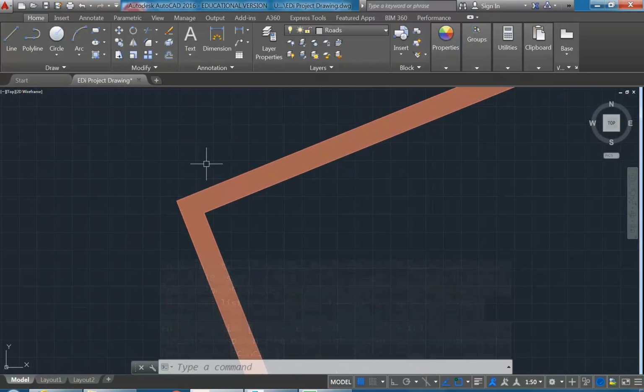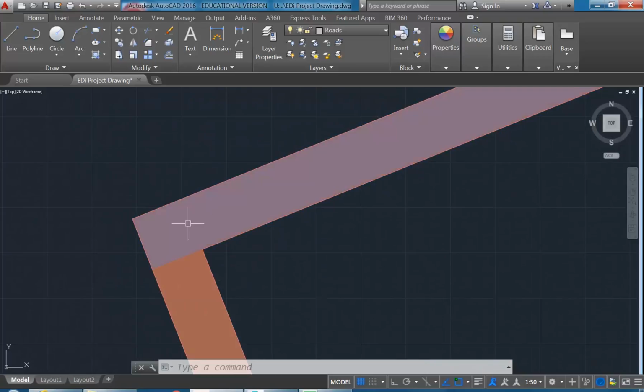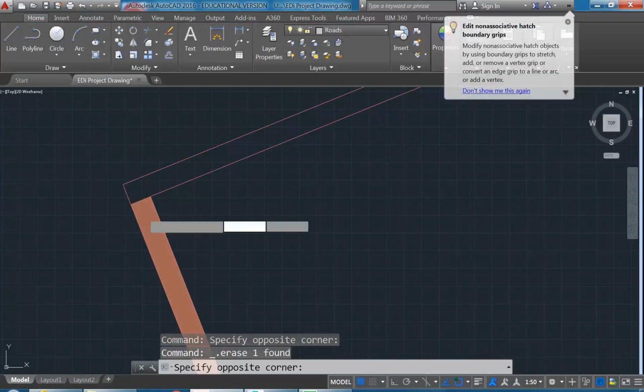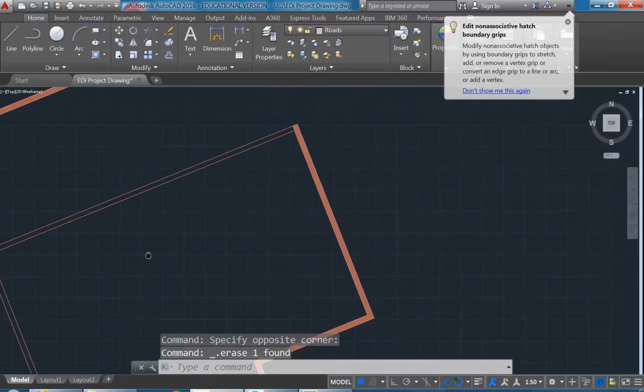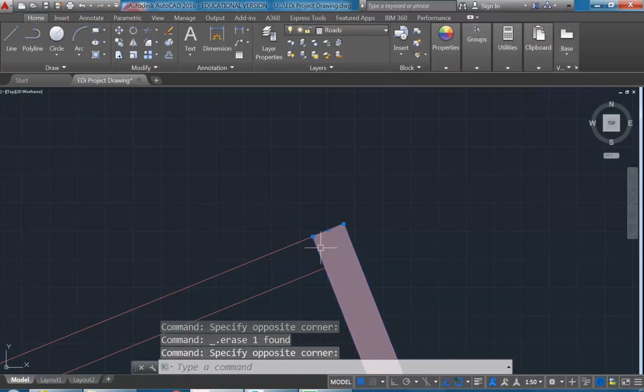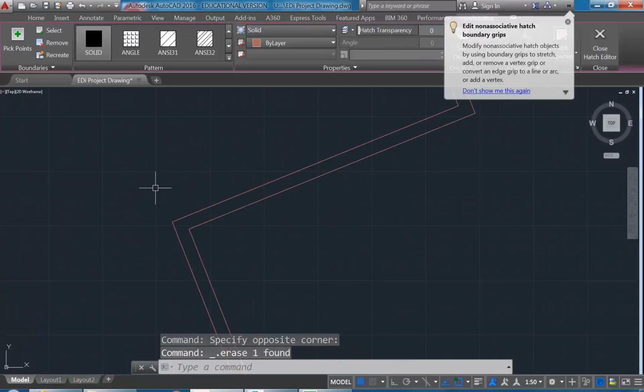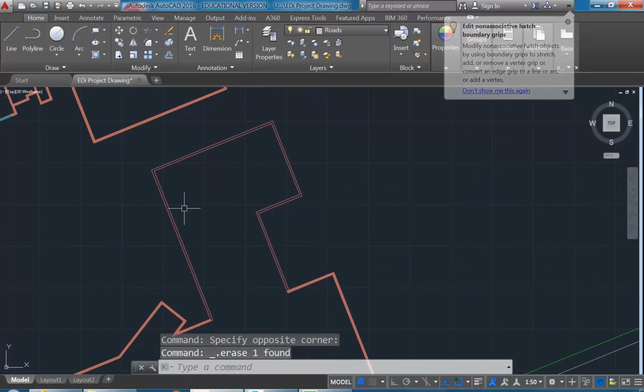And then you can see I've drawn my walls with the hatching. Now we haven't really looked at hatching much yet, so I might delete that and leave it with just the line work. We can come back to redo the hatching anyway. So I'm going to take all of the hatching away from those walls there.